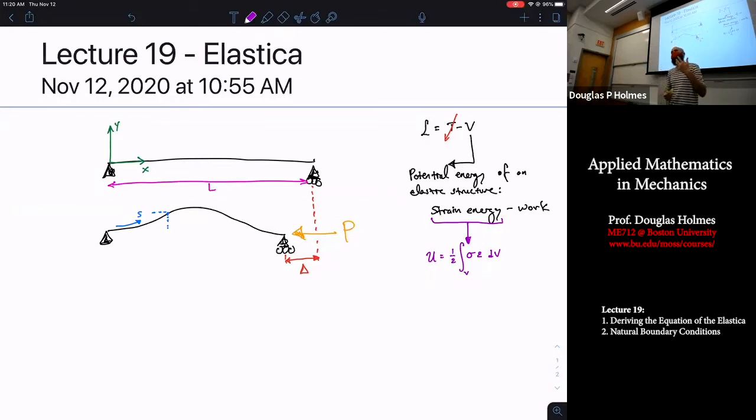And that's indicating to you that you have a material that's so easy to plastically deform, yet you're doing this large deformation and you don't really crease it at all. That must tell you that you're really not imparting much strain on the material. Otherwise, you would have expected it to fold or crease or leave a mark.